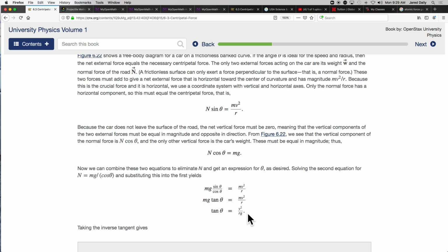Well, if you go in at a different height, so your R gets bigger, if you go in higher, then your speed has to be higher, right? So if you go in higher on the turn, then your speed has to be higher, but your distance is also longer. So you've got a little bit of a problem there. But if you go in high in the turn and then you come out low on the turn, then your R gets smaller, right? And you can waste a little bit of tire to pass somebody up. So you can take advantage of speed in turns, right? And that's what they do all the time in racing.